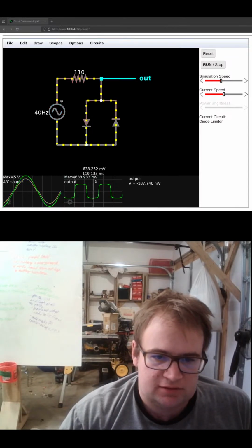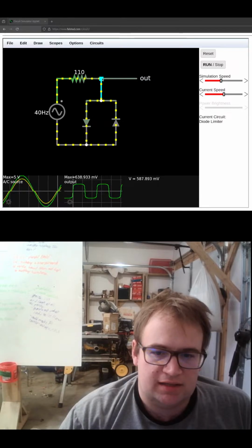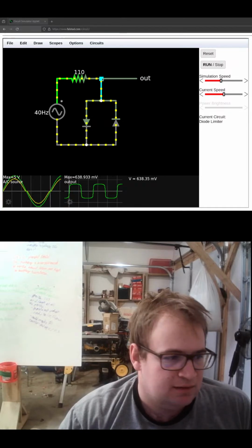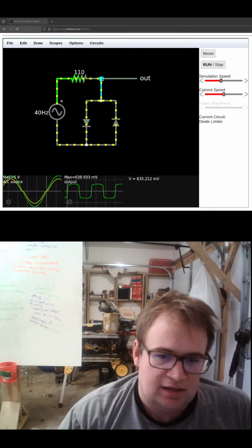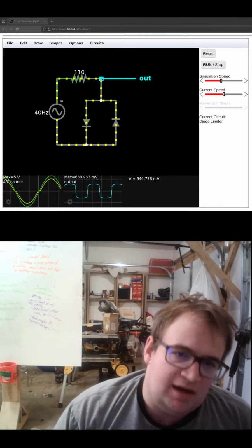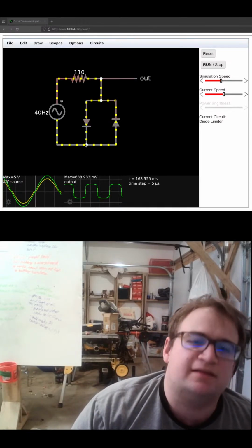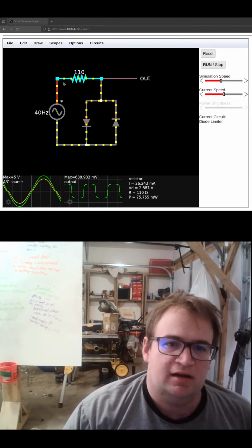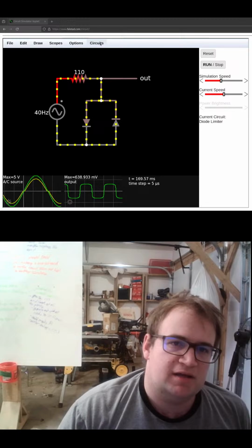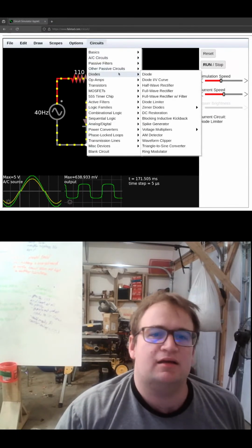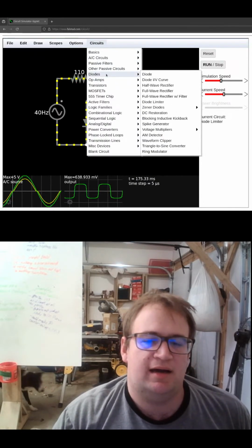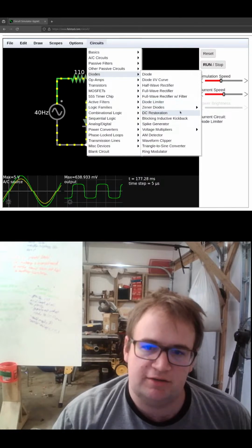Anyway, so what it's doing, this is outputting what? Yeah, so 5 volts. So right here, you see we're not going to get moving until we get above that 0.7 volts, which is the diode drop. And at that point, oh, I see. So it's only going to really get to 0.7 volts, that diode drop there. The rest is going to be burnt up along this resistor. I see, that makes sense. That's why it's called a diode limiter. It's sort of like what I was thinking they might be talking about, which was a diode clamp. I should have actually seen that before.